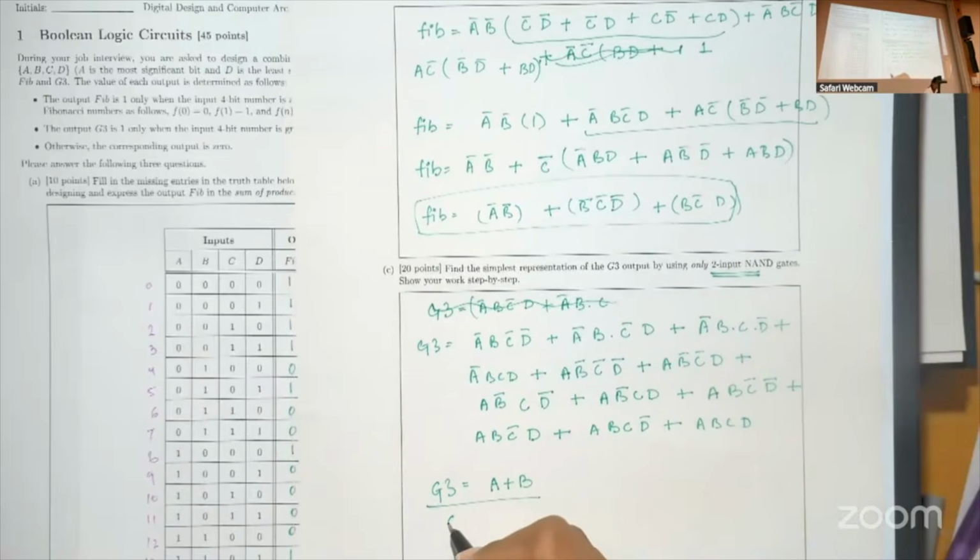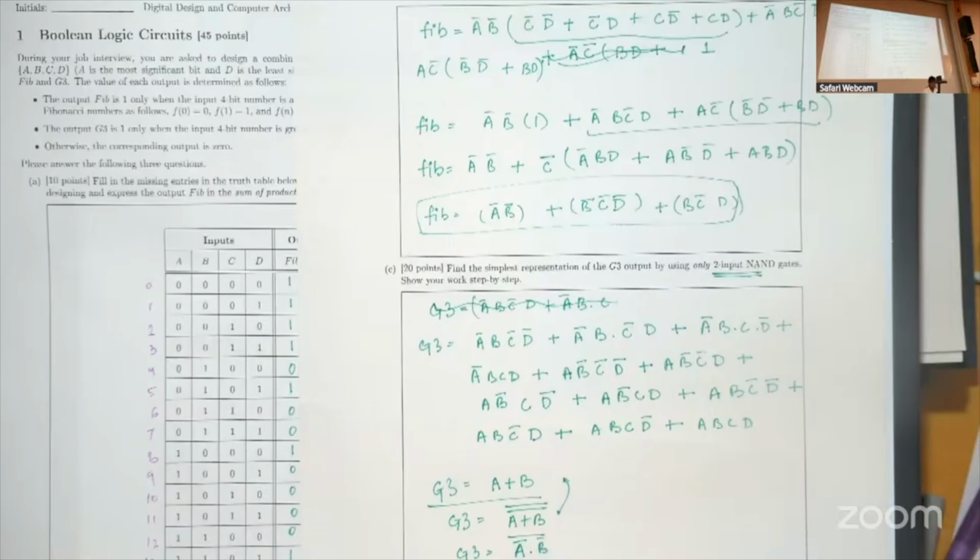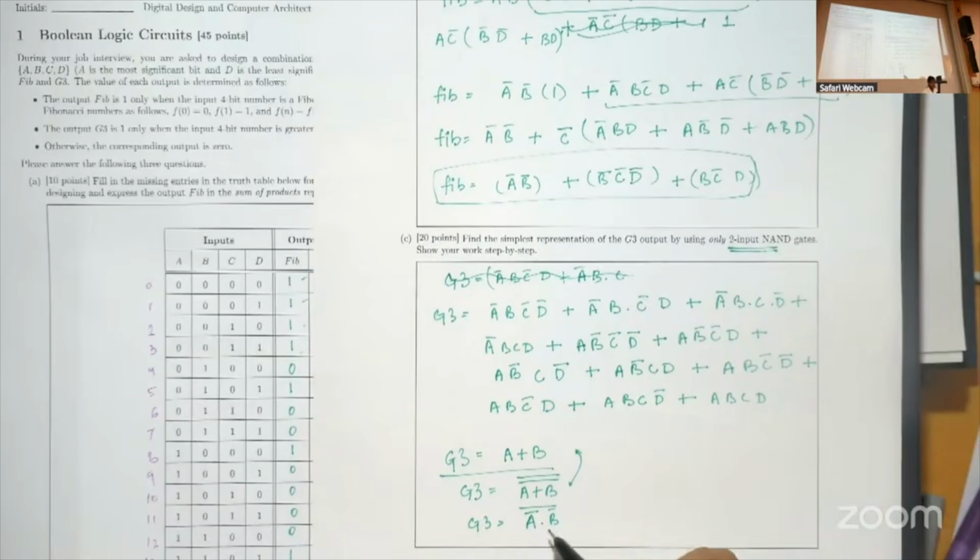So since we want NOT, because NAND has NOT and AND, we can start by taking the NOT of this. And if we write, then these two are equivalent terms. You can also write this as the complement of A like this. So you can also write this as this, but now it has 2 NOT gates, and we do not have any NOT gates. We only have NAND gates. So you can also write this A bar as A into A, the whole bar.